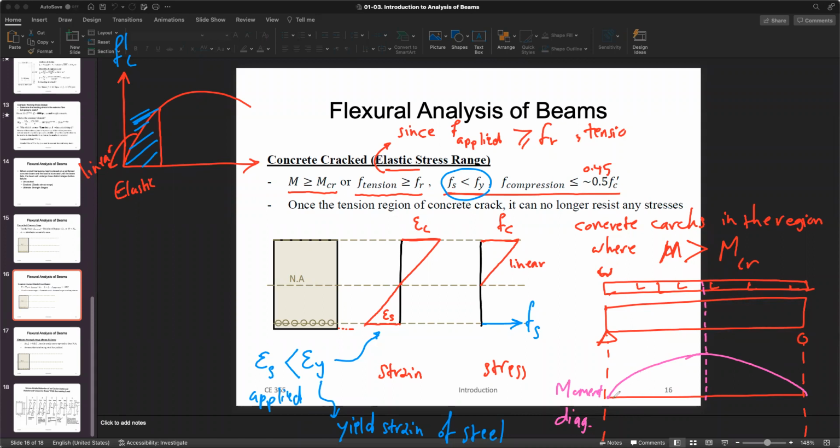So as you can see here, the applied moment would be different, right? For example, the cracking moment probably would land here, value-wise. So it is the cracking moment, right? So on these regions above that, you're going to have a scenario in which you'll see cracks on the tension side. It means, for example, at this region.